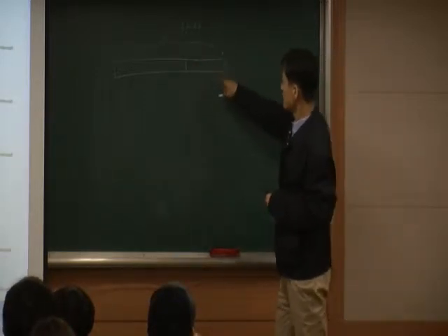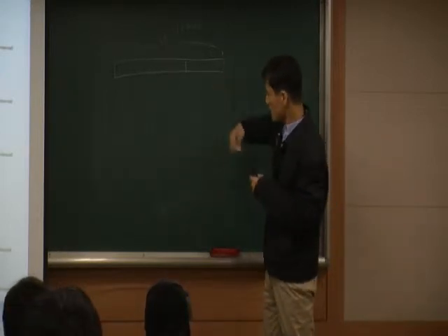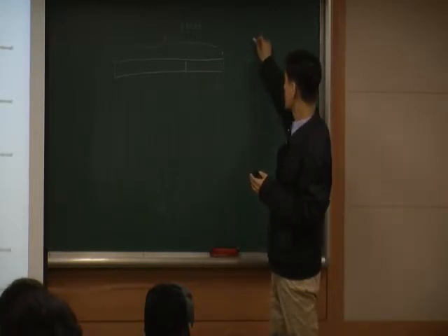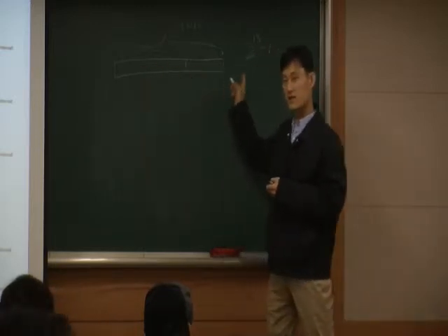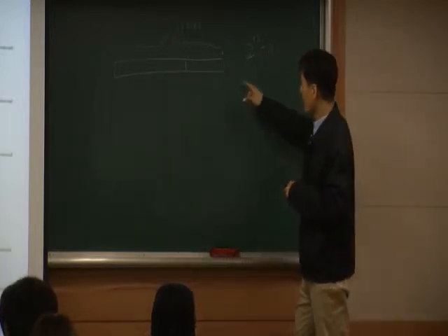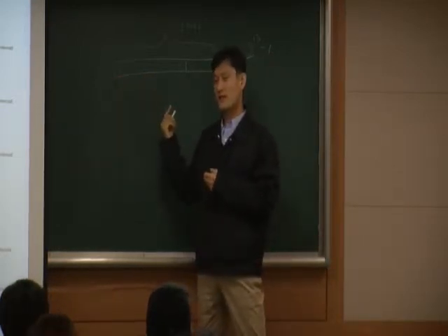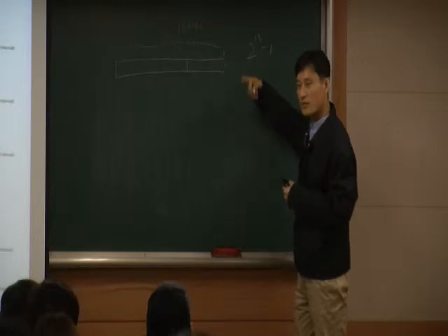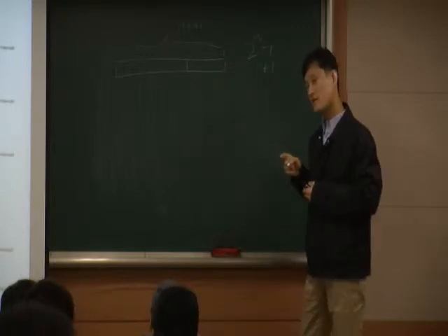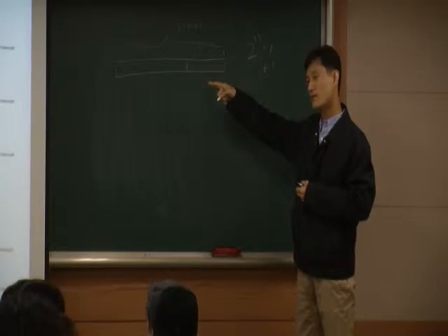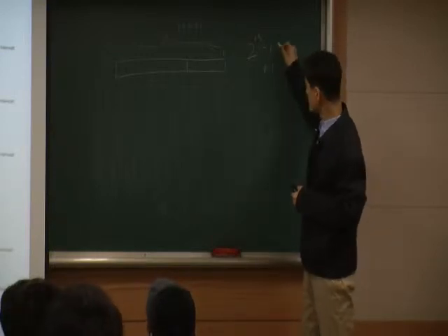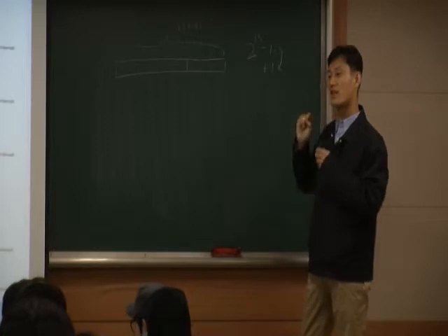So using this one, if you start from all 0, then it's just incrementing, and when you have all 1, that's the maximum value. When you have all 1, that's going to be 2 to the 13 minus 1. This is the maximum value you have. And let's say we have one more pulse coming in. In that case, this timer will automatically increment. Then what's going to be the value? It becomes 0. And we have a carry now.